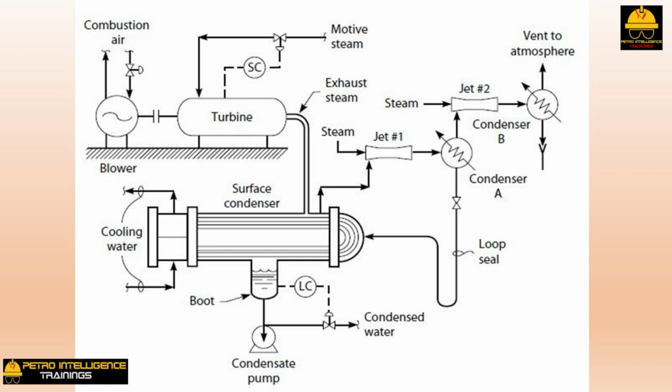The problem with this new air blower was that they could not bring the turbine speed above its natural harmonic critical speed. The critical speed of a turbine is stamped on the manufacturer's nameplate. Turbines are typically run well above their critical speed. If, for some reason, a turbine is run close to its critical speed, it will experience uncontrolled vibrations and self-destruct.